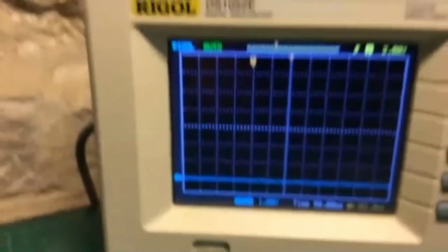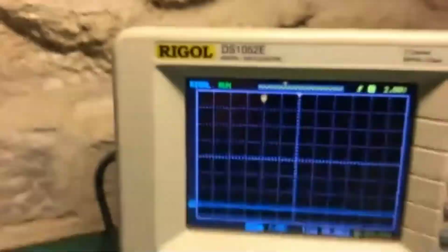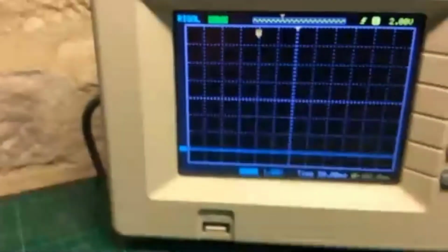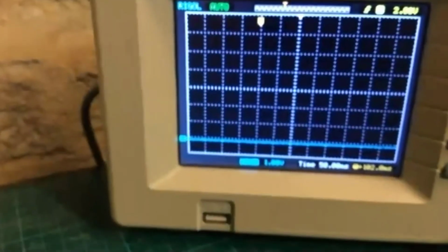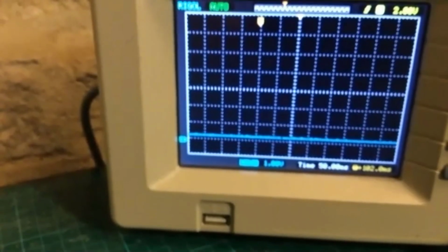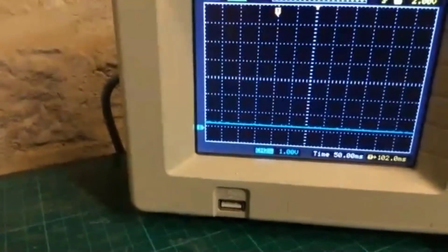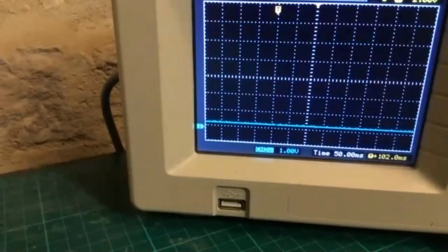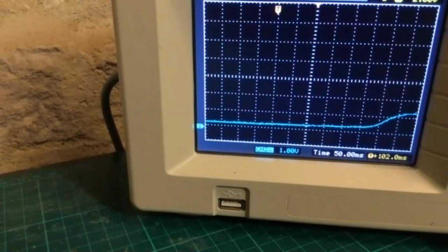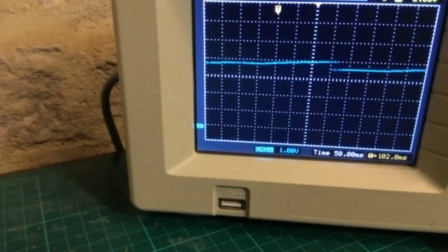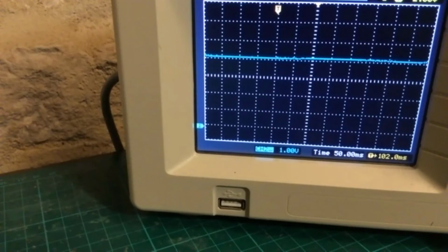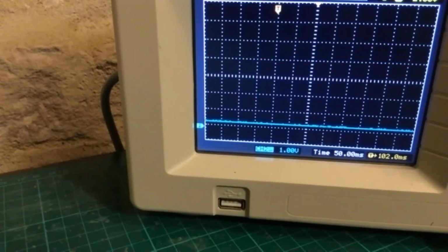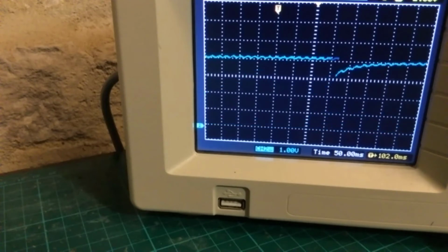Okay, let's go to the scope. Switch on, that would help. Okay, the scope shows you the ambient light level. Now, if I put my hand over it, it obscures the light and the voltage goes up. So that's what the ADC is looking at. That's with light, without light. And you can see that that's fairly clear to see.